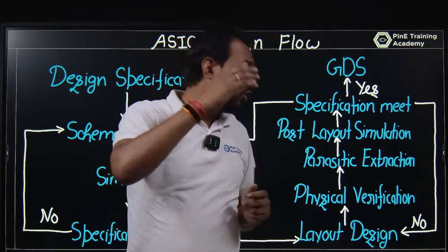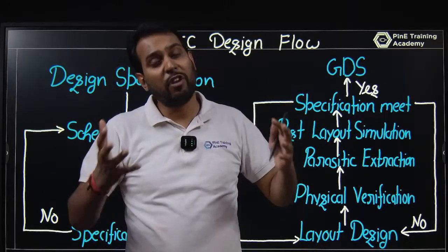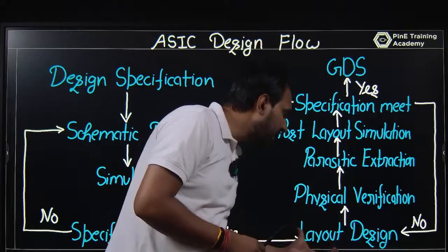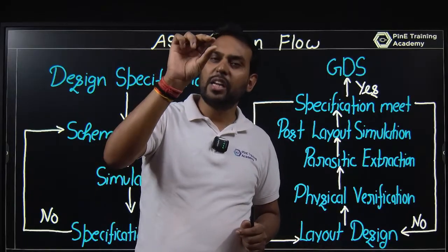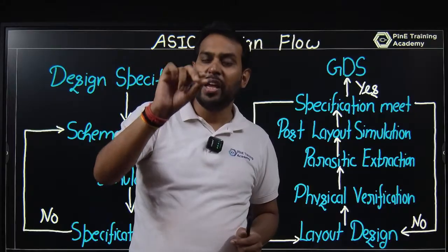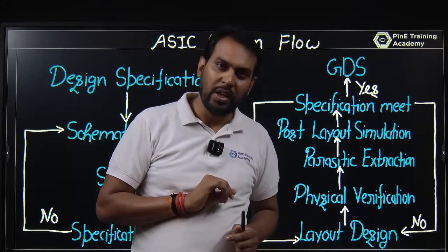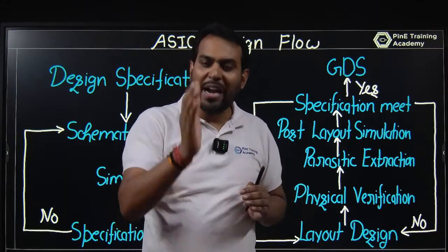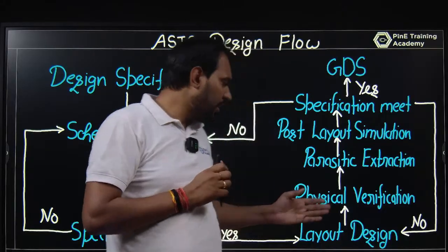And if you are using a higher spacing, of course the power will be wasted. Whenever you are designing a layout, we will always focus on arranging the transistors in such a way that we provide a minimum spacing, minimum routing space. Arrange the transistors in such a way that you find that minimum space. So that is the way.